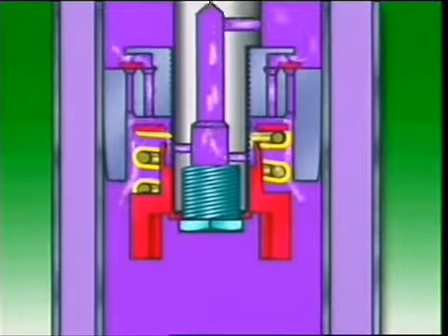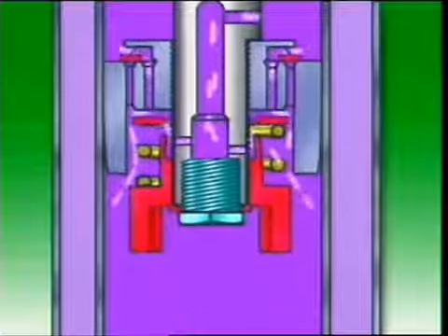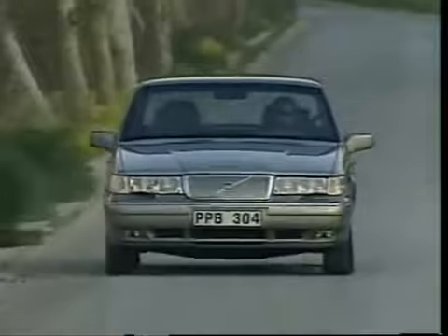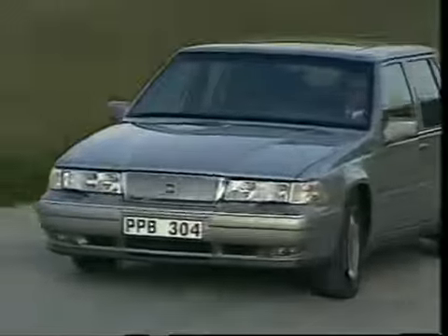The spring force applied to the valve is also reduced to allow the valve to open more easily. This means the oil can flow through the valves more easily, which gives a softer ride, but can also allow more rolling and pitching of the body of the vehicle.